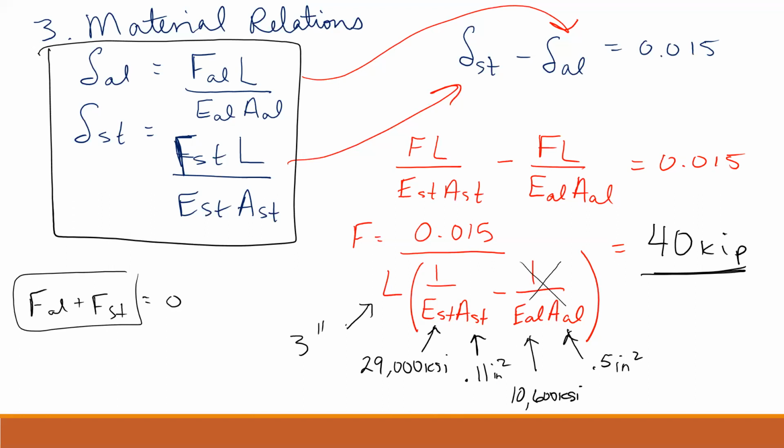But if you do that, then you have to leave your elongation statement real general, because you have to let that also be governed by your solution, as opposed to up here where we forced this aluminum to be contracting through that negative sign. Cool.